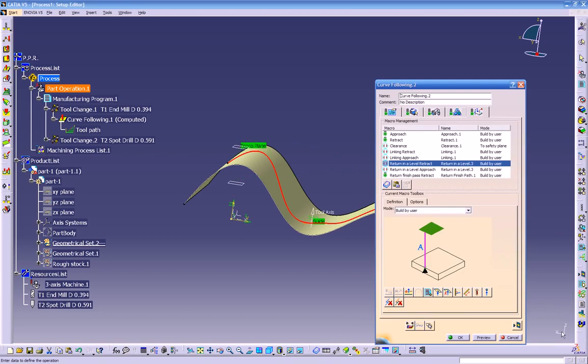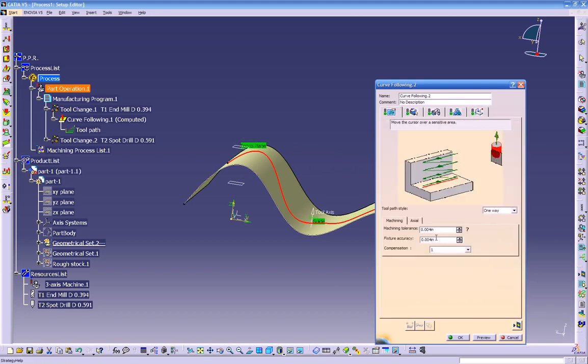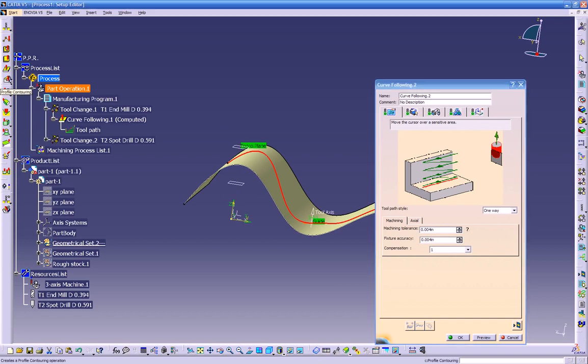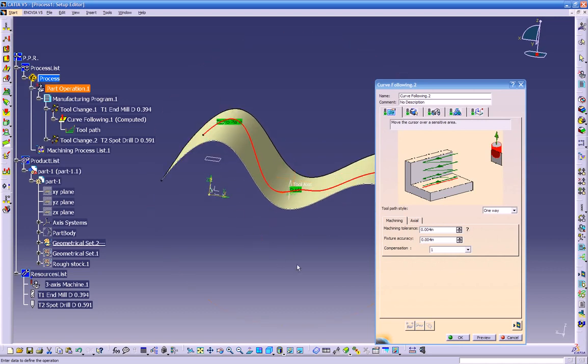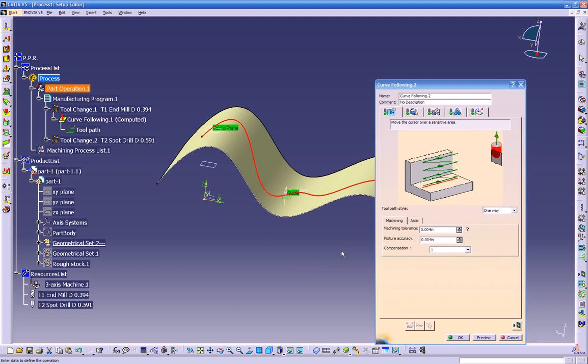That's how this works. That's following the curve, I meant, not the surface. Because we have another option later on, which comes in here. If you click in here, it's called multi-axis curve machining. And this option over here will help us to follow the surface without projecting this curve onto the surface. I'm going to show you a quick operation to show you how that works.